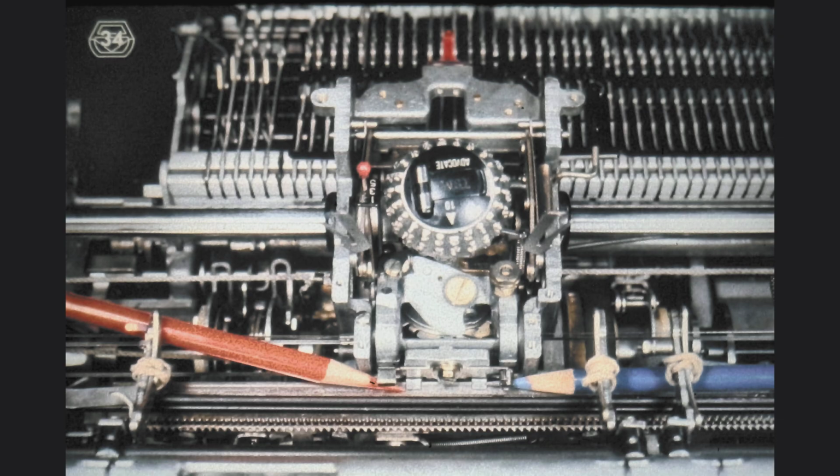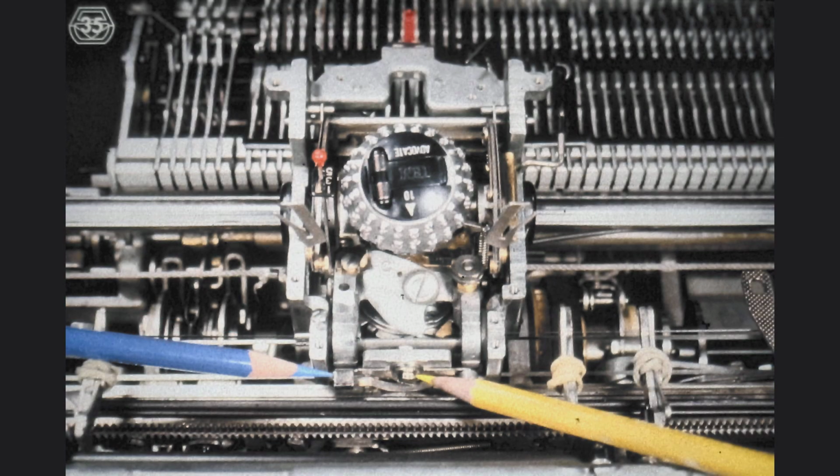Whenever a machine comes equipped with a bracket and spring only, there isn't any need for a vertical clearance adjustment at the rear of the carrier. All we need to do in this case is adjust the position of the bracket so that the lugs situated above the rack are also parallel to the rack. Selectric II machines are also equipped with this bracket and spring only.